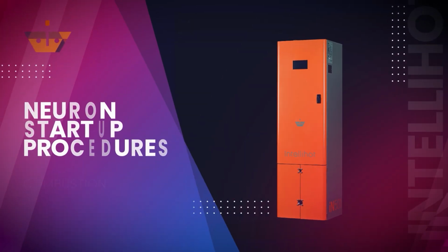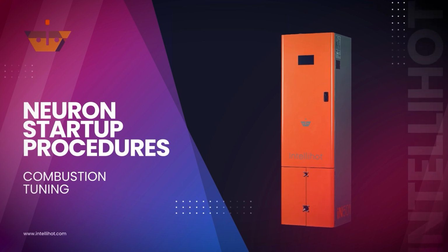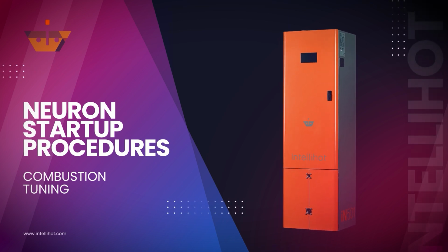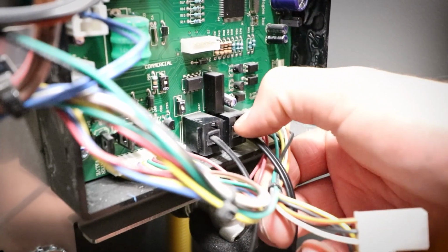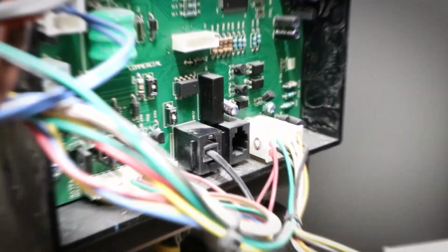In this video, we will be performing combustion tuning on the Neuron unit. Before starting combustion, make sure that the unit is not cascaded with any other IntelliHot units. If your unit is cascaded, disconnect the cascading cable between the units before continuing.